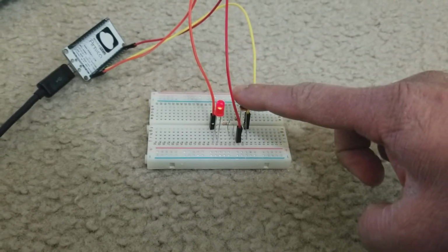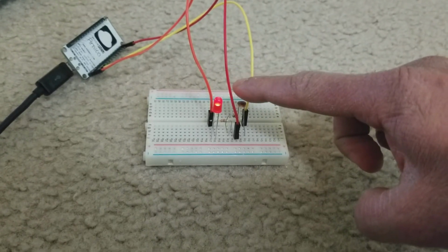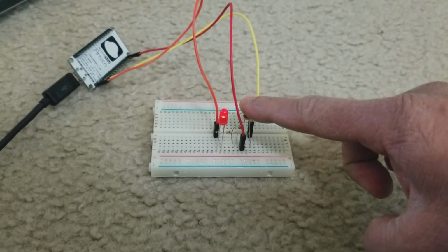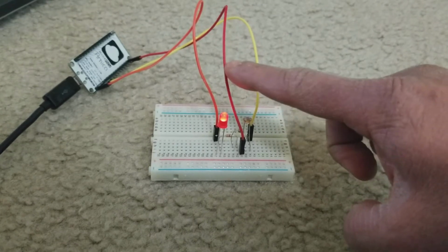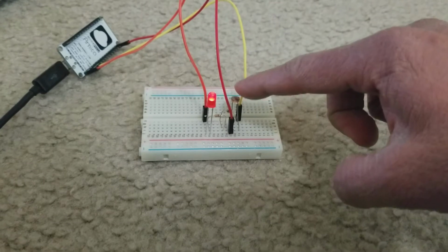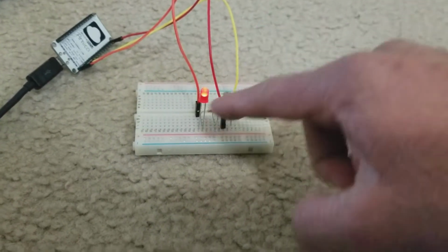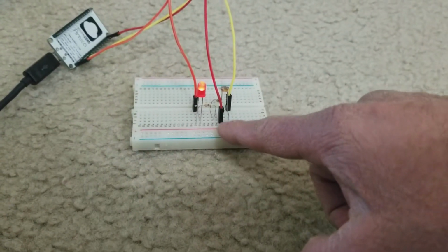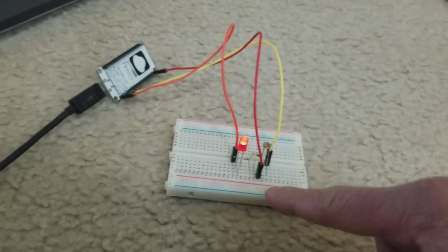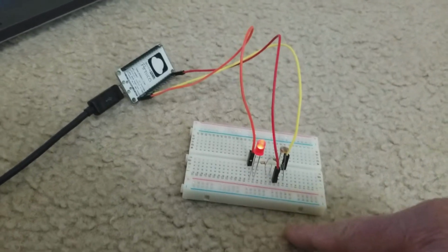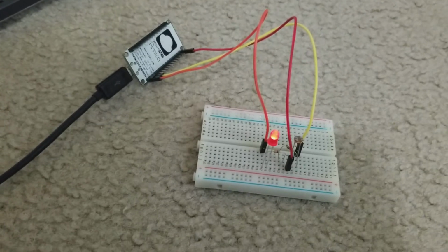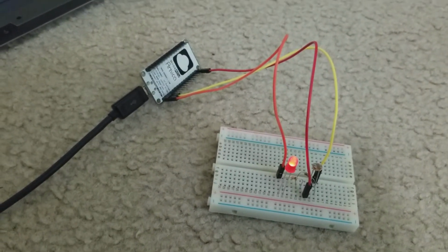So basically what's happening here is the resistance of the photoresistor is changing, which changes the current in the circuit, and since the current and the resistance are changing, the voltage delta across this photoresistor, depending on the circuit, the voltage that I'm reading is different, and hence the reading will be different. So let's look it up on the serial monitor here, what the numbers are.